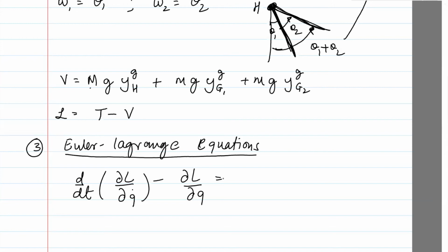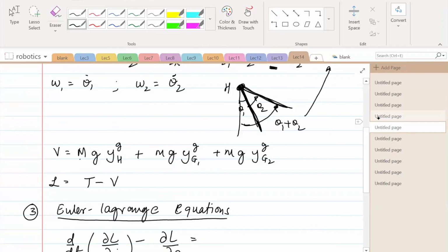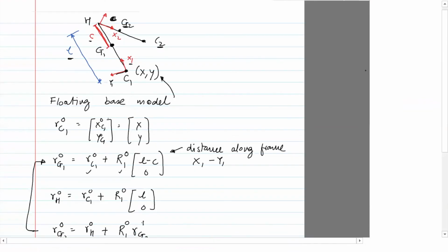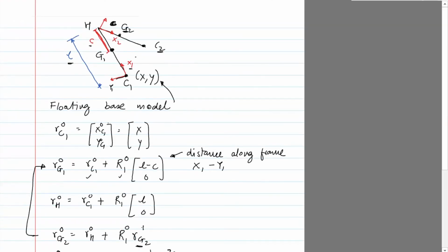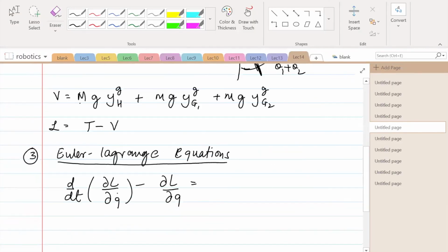In this case, we are looking at a system which is a floating base. So again, what is floating base? Instead of anchoring the robot to the ground like we did for a double pendulum, I actually let it float in the air, right? So C1 is not anchored to the ground. When there is a system like this, which is floating, and in reality it's not floating, C1 is attached to the ground, I actually need to introduce what is known as a Lagrange multiplier to the Euler-Lagrange equation. So the equation is modified.